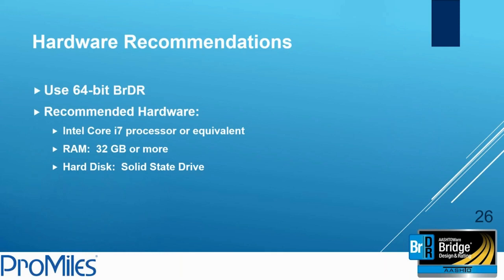We also recommend that if you cannot increase your RAM, you can probably talk to your IT and work with your virtual memory to provide more memory space when you are running an analysis. And we definitely recommend having a solid state drive, a drive to which all your output files are getting dumped.